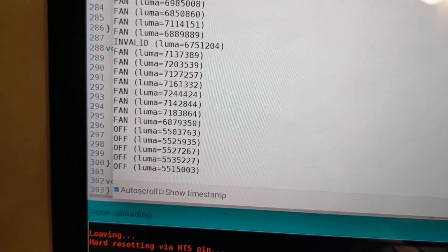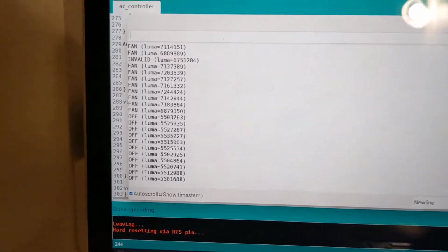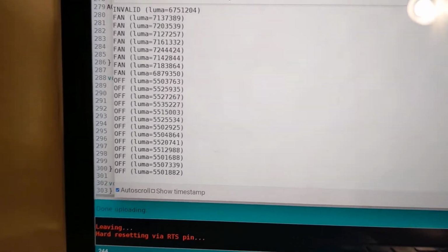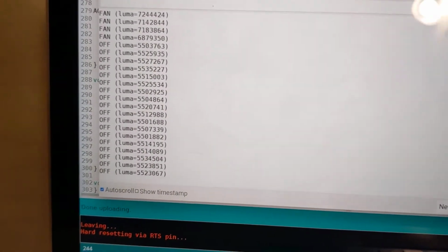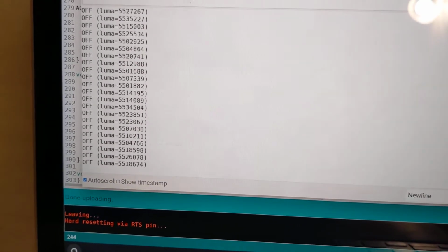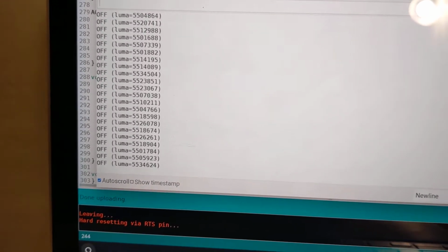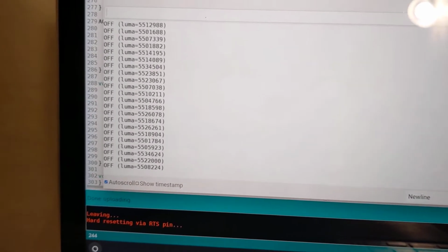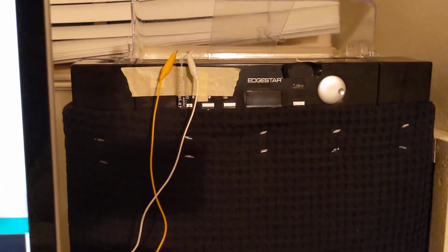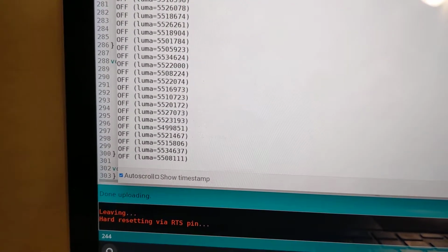So basically this is the basis for an automated controller. Because if the ESP32 can figure out what mode the air conditioner is currently in, then that means that it can kick it into the correct mode when it wants to do like heat or cool over the network. I mean, the eventual goal is to have another ESP32 connected to a Nest thermostat that then sends relay outputs. So I'll just relay wirelessly to say, oh, the Nest wants this to be in cool or it wants it to be in heat. And yeah, that's basically it. All I need is some bidirectional control so I can tell this thing which mode to stop on.